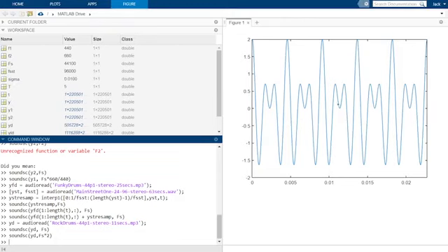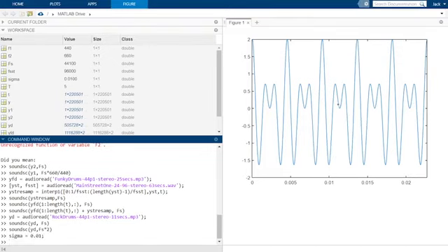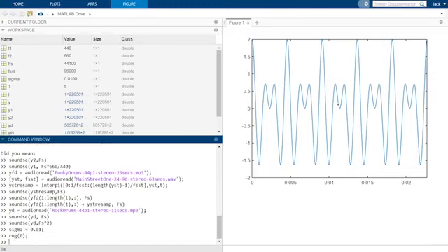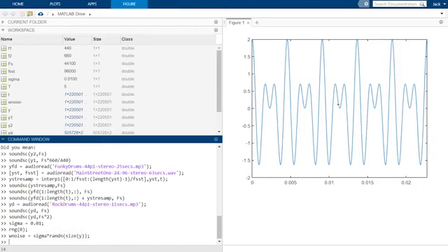It could not be easier to generate white noise in MATLAB. First, we define our standard deviation for our noise distribution, traditionally termed sigma, and seed our random number generator. Then we define our white noise as sigma multiplied by normally distributed random numbers in an array the size of our signal y. We can show the white noise signal in a plot. First, we move our two-tone signal y plot to a subplot.